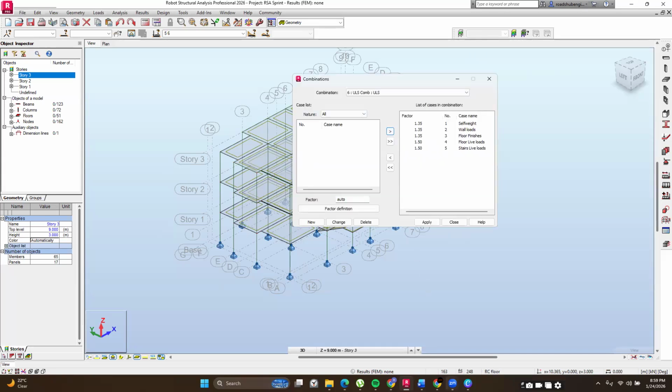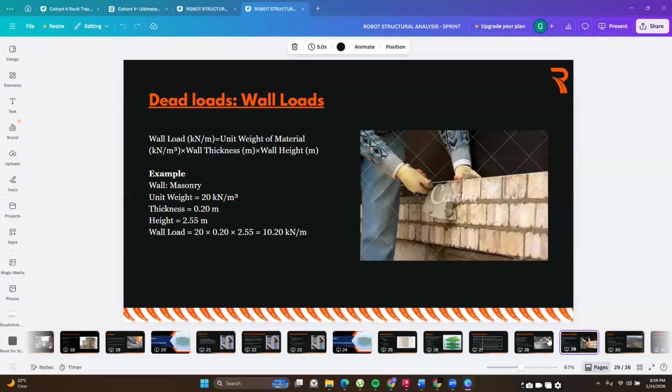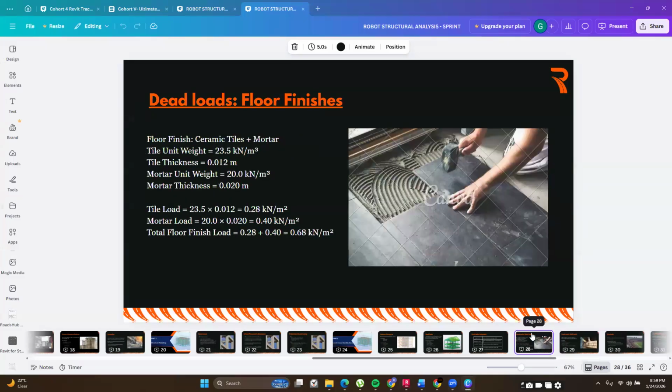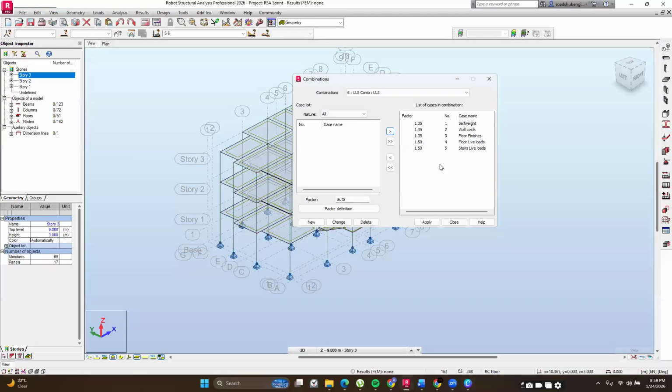Remember what we said yesterday. When it comes to loading your structure, you expect some uncertainties in the design. So when it comes to loading the structure, sometimes you have to account for the scenarios where certain loads are going to be exceeded from time to time. So there are times the live loads may exceed what you actually designed for.